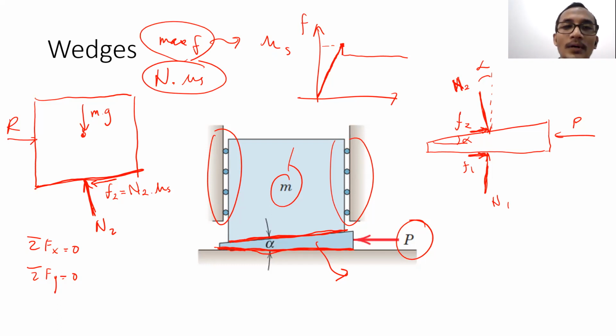Correct or not, Asar? So that's the principle that we are going to use for dry friction and wedge. When the question is, what is the force needed to move the things, the first thing you have to check is the maximum friction force, whether it can handle the maximum friction force or not. Because as long as it can handle the maximum friction force, yes, it will be able to move. You understand, Asar? Understood, sir.